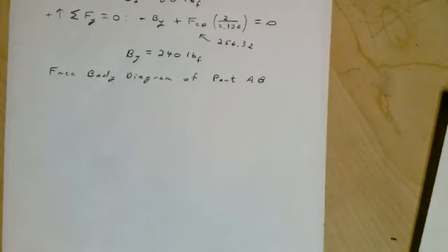And again, remember for the free body diagram, you need to show the part itself, and it doesn't have to be in great detail, but the most important thing, you have to show all the forces that apply to that part.